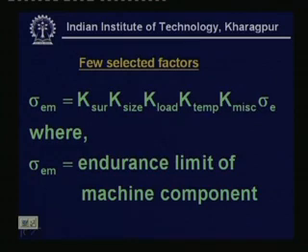Here we are considering some of the very important selected factors. Well, the word important may vary, but anyway these are certain major factors a designer is mostly concerned about, and all other factors we are just putting inside a K miscellaneous account, where one can choose from the list of Marin factors given in a standard design data book.